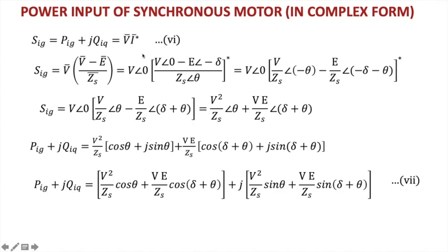that is the rectangular form, active power and reactive power. In the polar form, we can write it as V into I conjugate. I have explained before why we take I conjugate: when you simply multiply V into I, the angles will be added in the polar form. But we want the angle phi, because power is given by VI cos phi or VI sin phi, and that angle phi is only possible when we subtract the two angles.